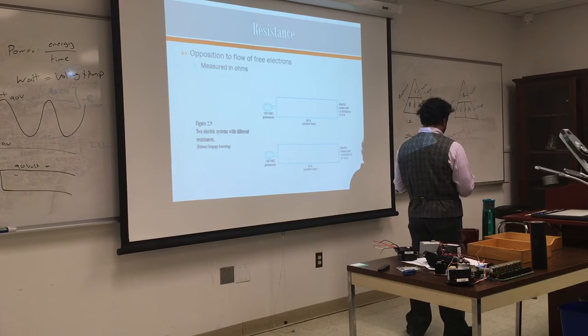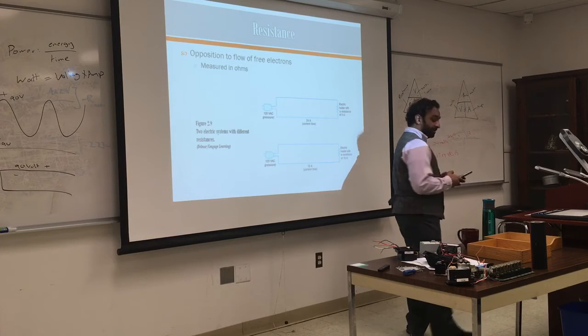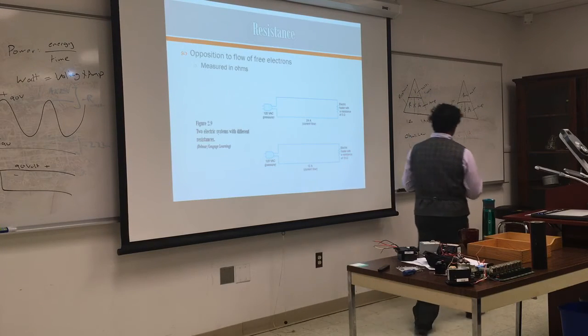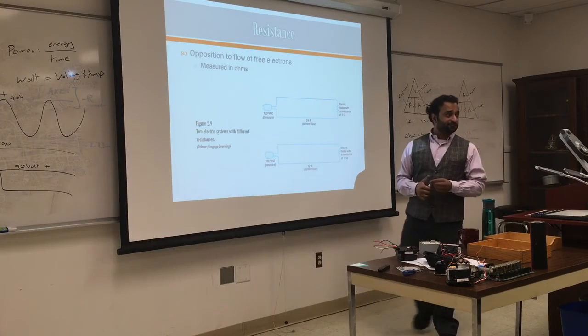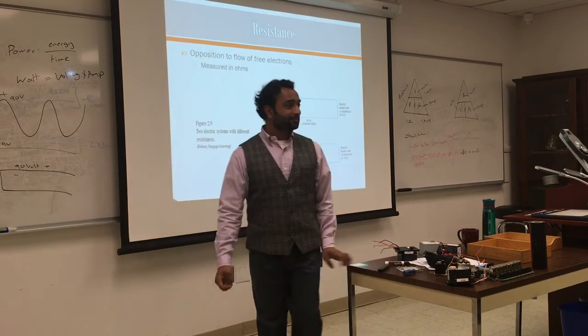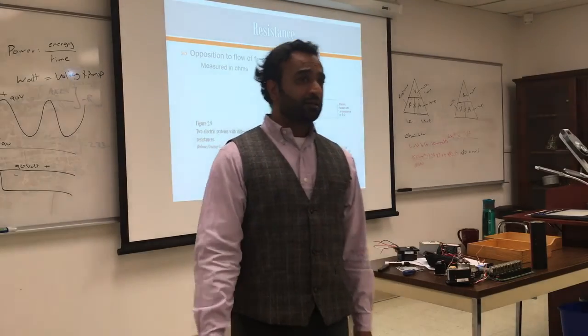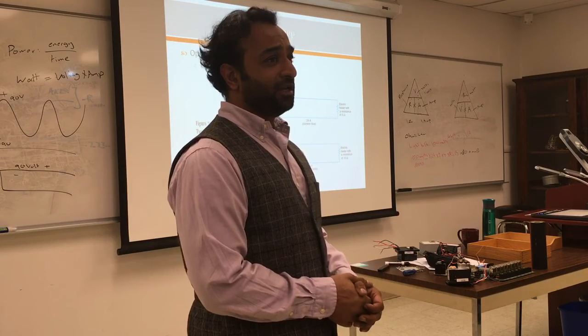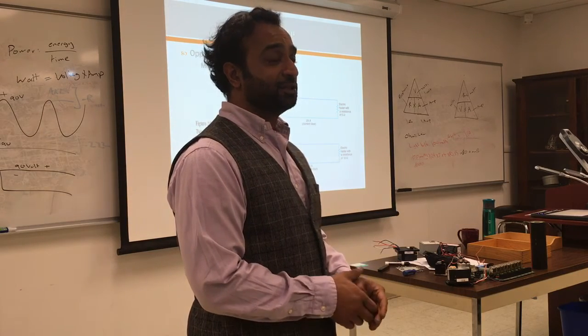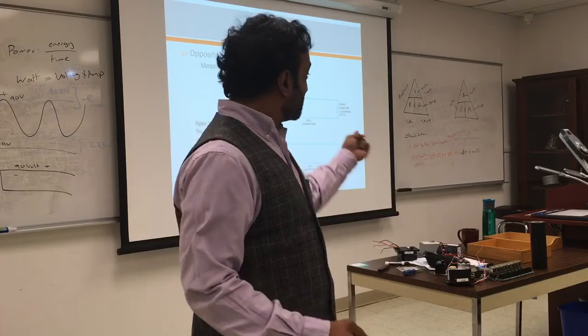This will give you how much this light bulb will cost you. 100 over 1,000 times 24 times 7 times 4 times 0.15. $10 a month to keep one light bulb on. That's a lot for one light bulb. So it adds up. We'll do a few examples to see how it adds up. You don't want your power bill to be this high, and if it is, you should understand why. But this is one light bulb.